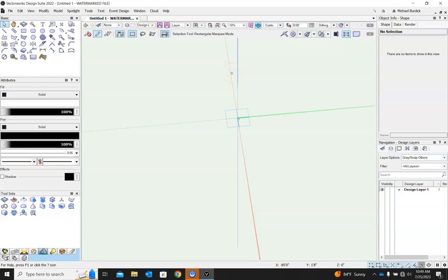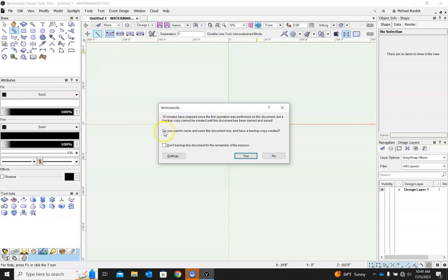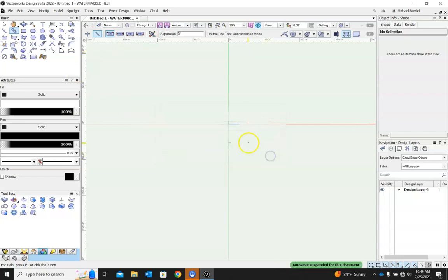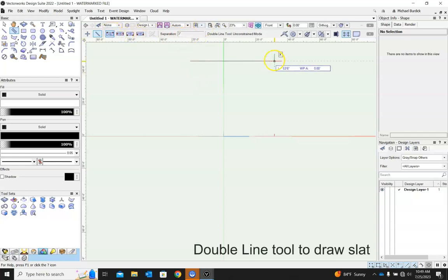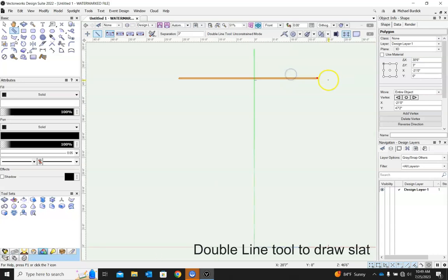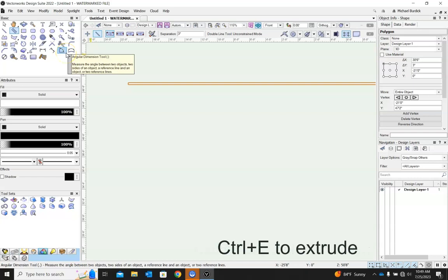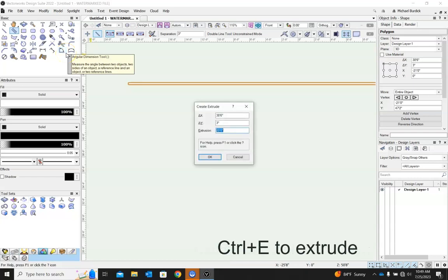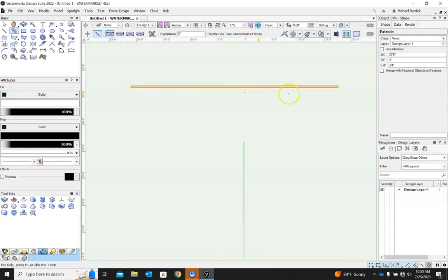For example, let's go ahead and say we want to make a little slatted moon piece. So we want a moon to rise upstage of something, and we want it to be made out of like an old slatted barnwood. But we don't want to draw all of these slats and things individually. So I'll draw one slat. I will extrude it. Let's extrude it 3/4 of an inch. We're going to make that out of a 1x stock. So there's our one slat.